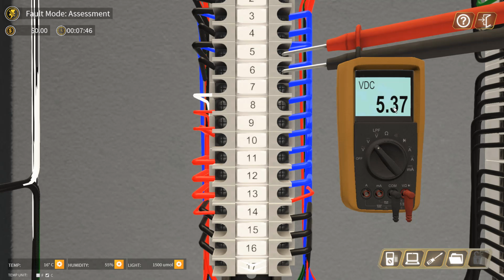It can be due to a problem of the PLC analog input channel, or it can be due to a problem of the transducer sensor, the humidity transducer. Okay, maybe the transducer has an open circuit or loose termination. When there's an open circuit or loose termination, it will have the maximum voltage drop at the humidity transducer. Thus, it will give you a higher humidity reading at the PLC side.